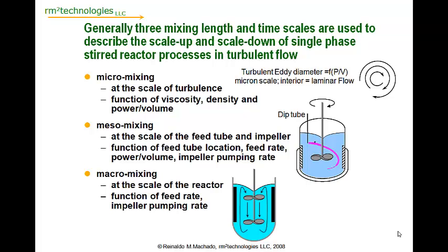Macromixing really occurs in the overall bulk of the reactor, and this is the scale of the reactor and is usually a function of the feed rate and the impeller pumping. And this has to do with the overall dilution of the feed within the tank.